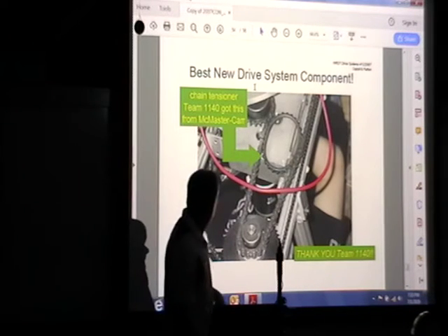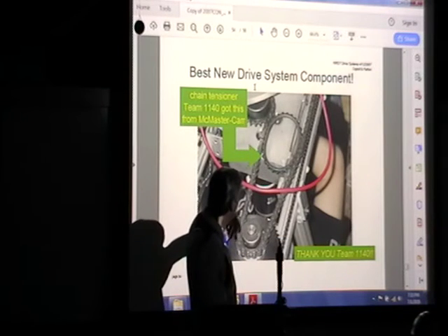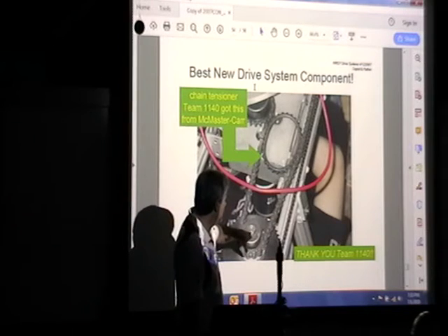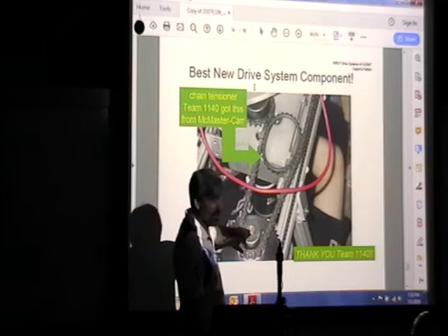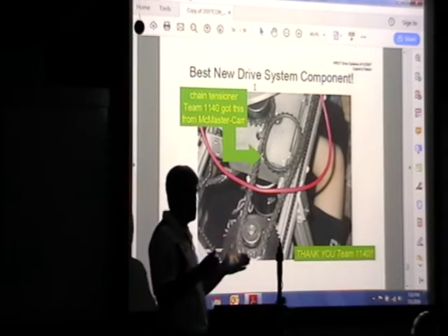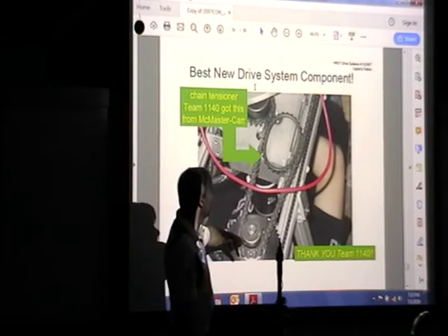Not sure why they threw this picture in here, this is a cool little chain tensioner. But, in this case, they've got some unsupported shafts here. Now, like I said, this is potentially okay, as long as they've sized the bearings on the backside and got enough distance between the bearing sets to handle any kind of load that this is putting on.